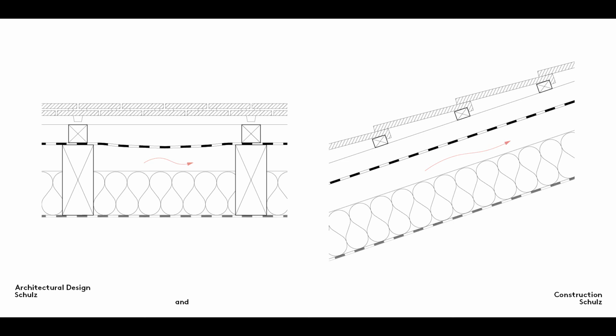Next, a vapor barrier is laid over the insulation. This foil sheet retards water vapor diffusion from the inside and is necessary to prevent the buildup of condensation in the insulation material. It is very important for the vapor barrier to be laid across the entire surface of the roof with no breaks, and so the joints are taped together. This layer also makes the roof membrane windproof.